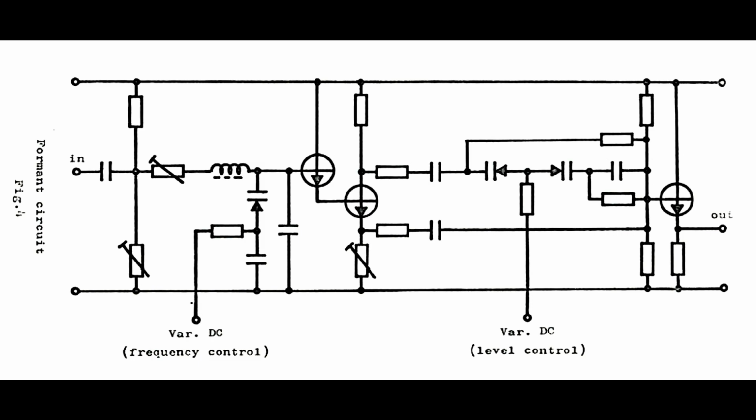So there's a positive phase and a negative phase, and then it goes via two capacitors. One is only a DC blocking, that is the top one, but the bottom one, its value is very important and very interesting. And that value of that capacitor is exactly the same as the sum of all the varicaps on top.